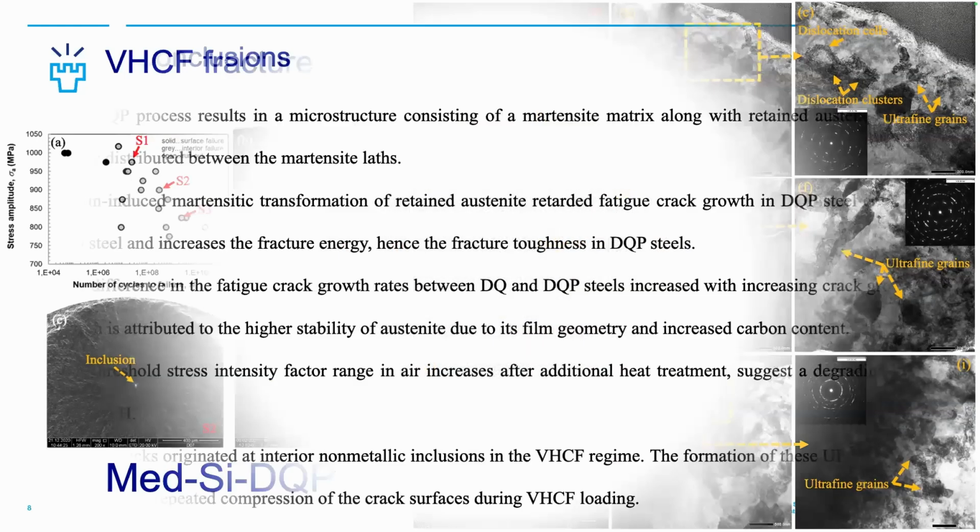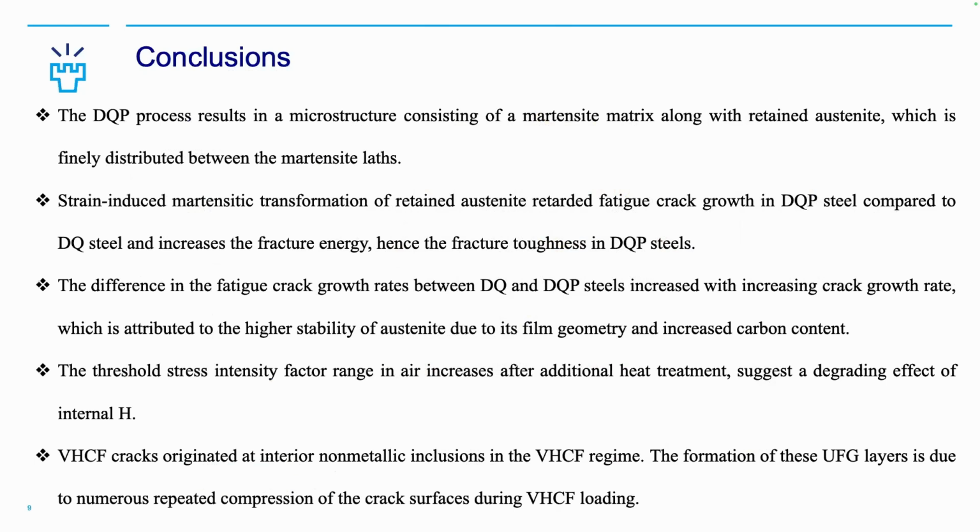Okay, so overall, I'm not going to read it, but the overall conclusion is that rather than trying fancy microstructure, we should take care of the level of inclusion during the casting stage itself. So if we control the inclusion, then this fancy microstructure would help.